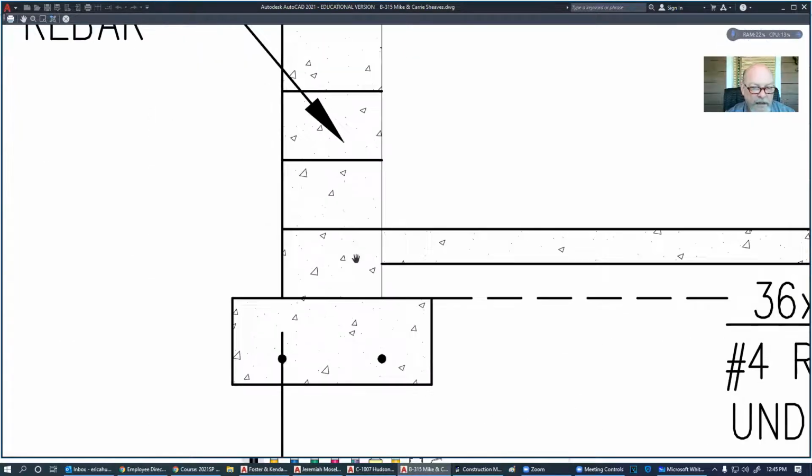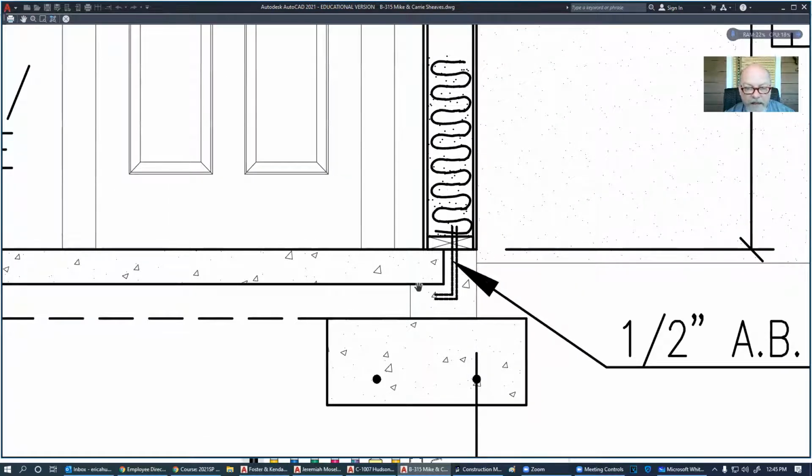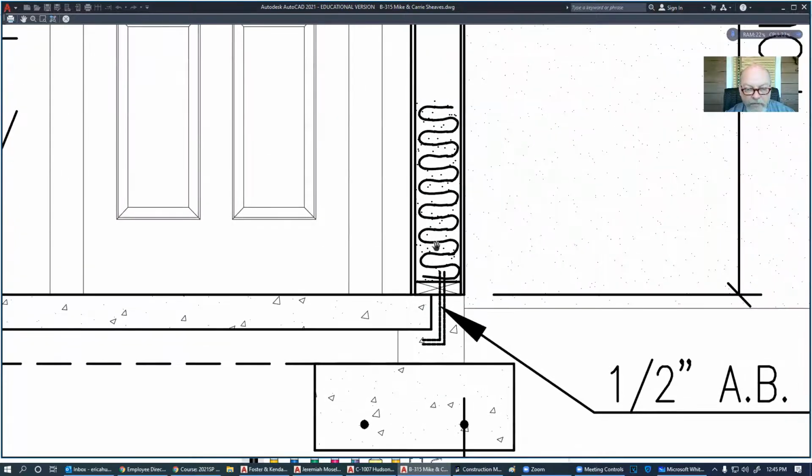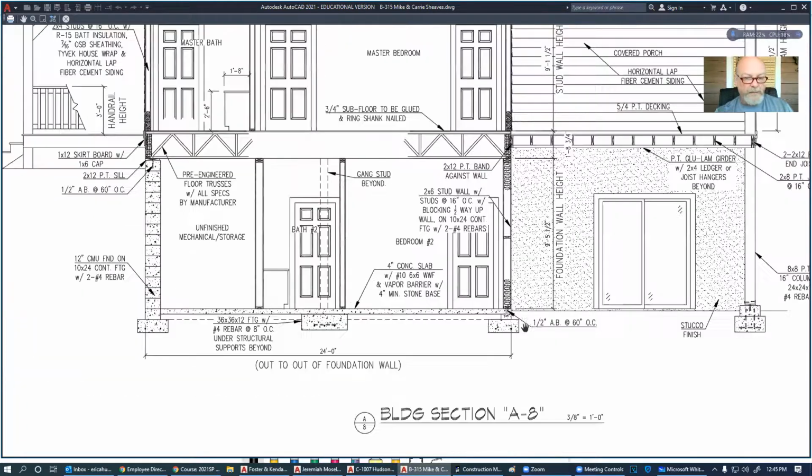Notice on this side, the foundation wall is independent of the slab, even though on this side where we have a daylight wall, the slab sets on top of the foundation, but then we have this wall that kind of compresses it down. This cannot float very good. You may actually see some cracks in this if this wall settles over the course of its lifespan.